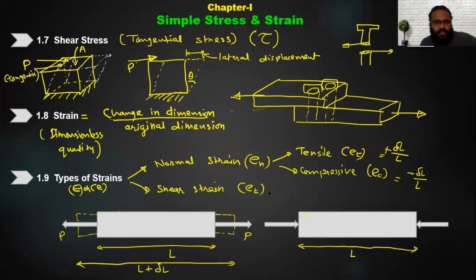Okay, now the shear strain. When we discuss shear stress, the shear strain causes a change in the shape. So look here, the shape is changing, meaning there is a lateral displacement over some perpendicular distance. You can see this is the upper face which is going to move and this is the lower face which is fixed. The perpendicular distance between the upper face and the lower face is, let's say, L, and the lateral displacement is, let's say, X. Then the shear strain, also denoted by theta, is approximately equal to tan theta, which is given by the lateral displacement upon the perpendicular distance.